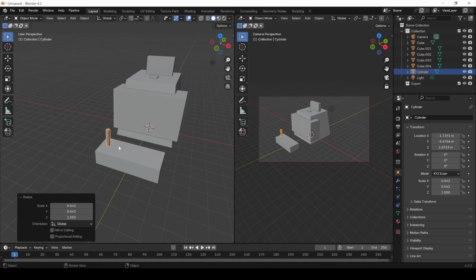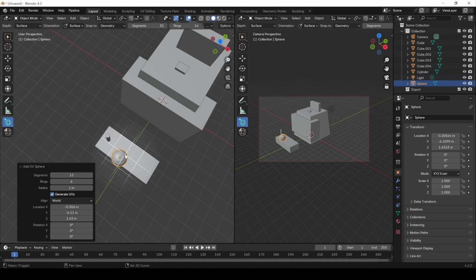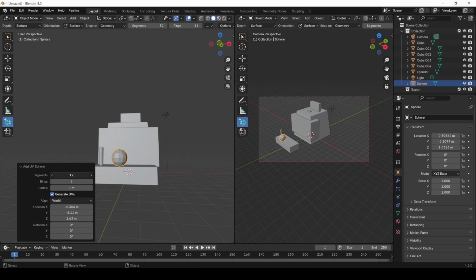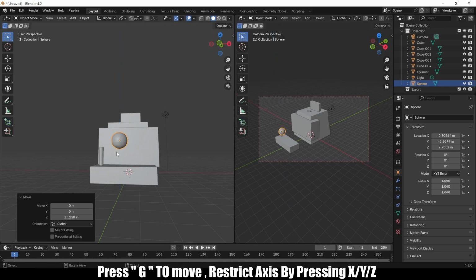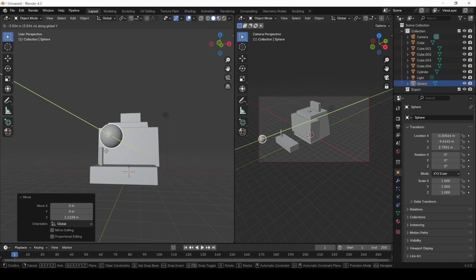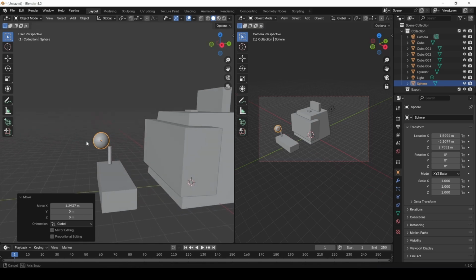So let's make it a little bit smaller like this, and let's just go here and go to sphere and just create a sphere. Hold Shift, then release and keep holding Shift and press again. Now you have this. Let's make it 32 with 16, and now we have this. So J and move it on Z, then J and move it on Y, oh I mean X, J and move it on X, and just something like that.